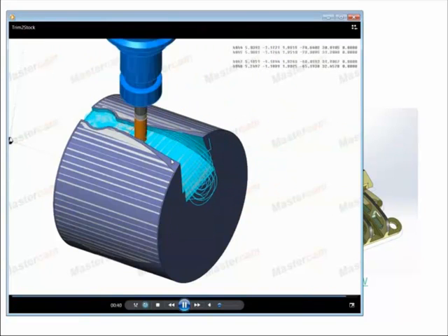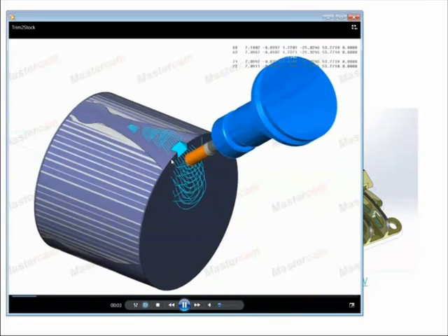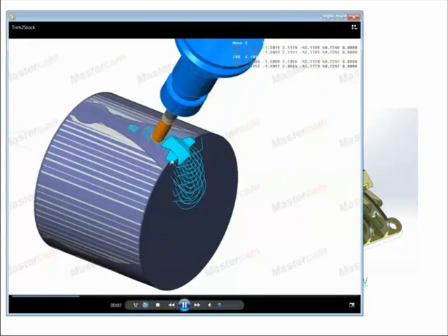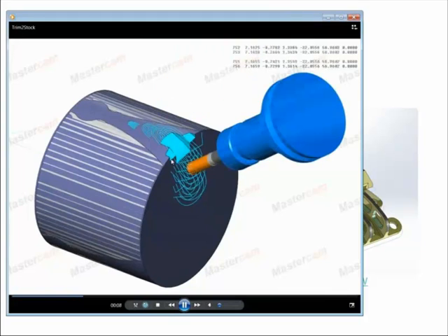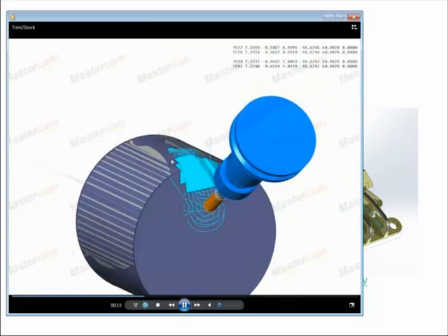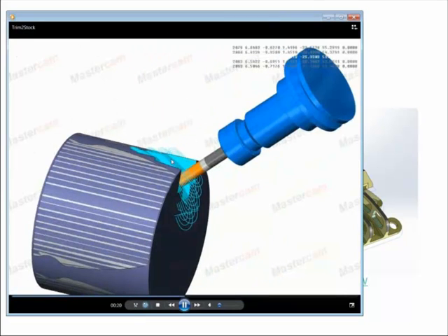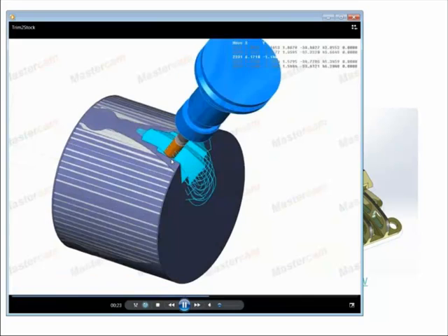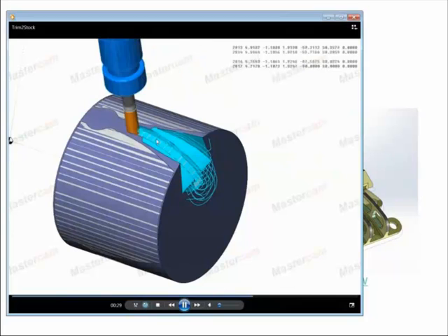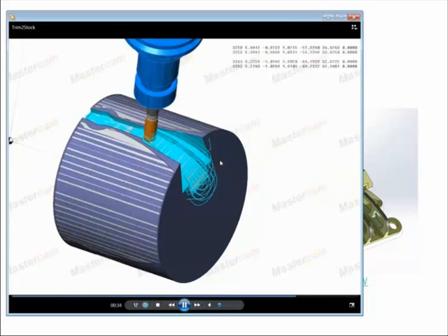Because otherwise, if we did multi-depth cuts here, like what we're doing, if I just repeated the bottom pattern 6-7 times, most of this toolpath would be cutting air. Right now, I said only run out so far out of material, so you can reposition and then blend spline between the motions. And we have stock model awareness, which can save you a lot of time. It can save over 50-60% of cycle time by just doing this.